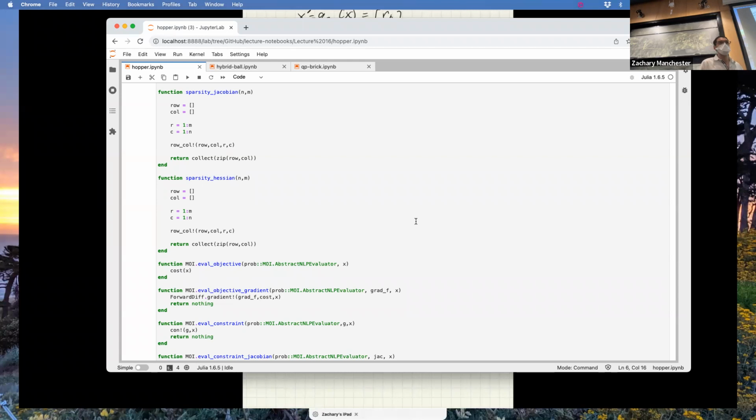I'm just thinking, do you run into the case where it's over constrained? Yeah, I mean, you definitely can. What I'm doing here, that reference thing, is in the cost function, so it's not a hard constraint. I'm not actually exactly following it. What I'm writing down in this problem is basically, here's this random sinusoidal thing I just cartooned out. Try to track that while obeying all the physics constraints. So it's not exactly following that. It's going to do the best it can and not really worry about it too much.